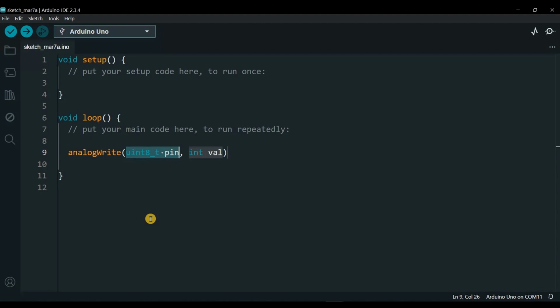It's just that the frequency of the PWM might be different, although for the Arduino Uno itself, the frequency is not fixed for all the PWM channels. This is what we will see after this. However, if we want to change the frequency, we still can, but it doesn't have much impact on the output.